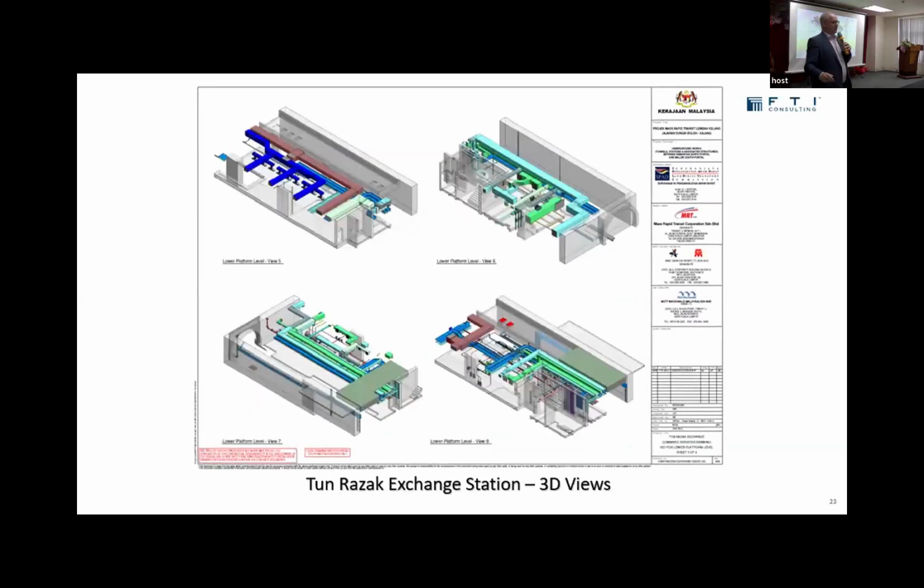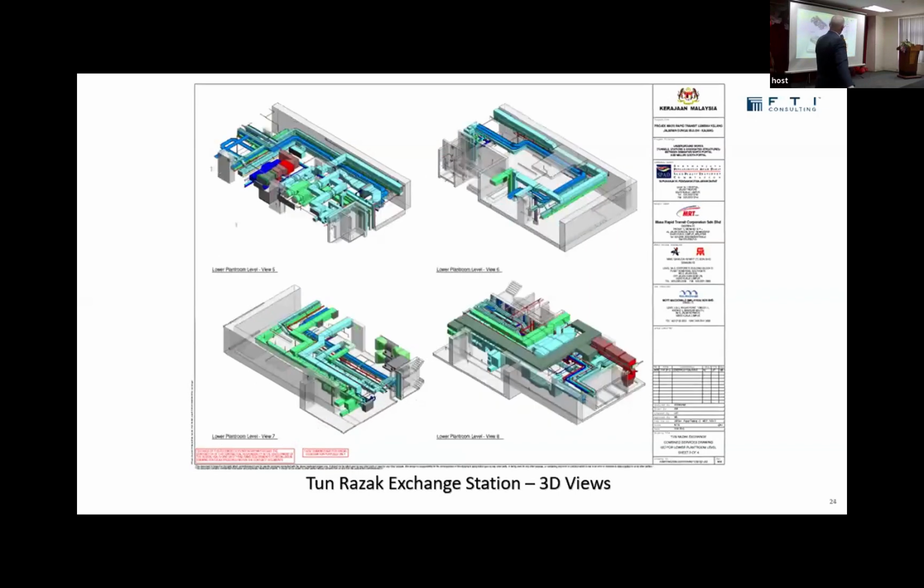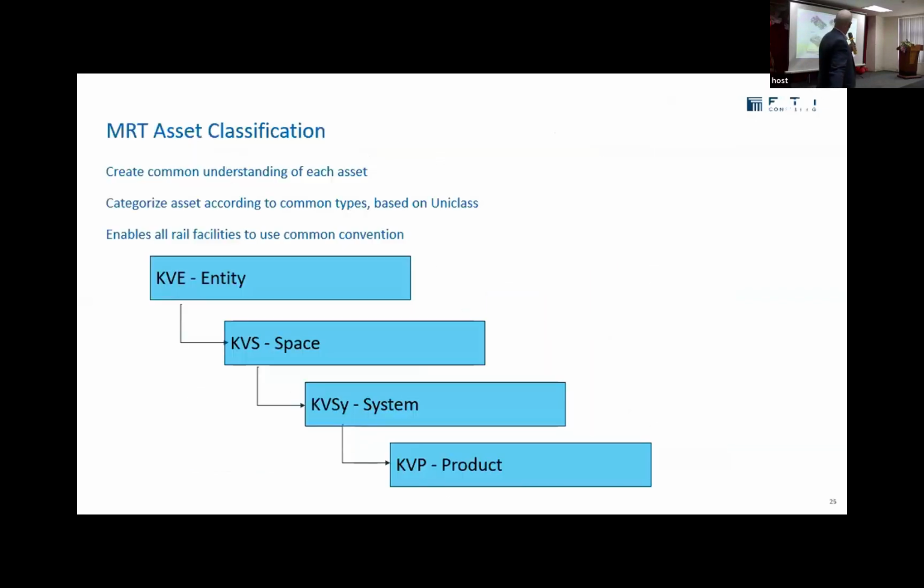But what's most important, and this is a challenge I'm going to set for you, on your next project, don't just settle for traditional 2D drawings. The plans, the elevations, the sections, that's easy in Revit. Also ask the design team to include isometric views. And you can do it per plant room, you can do it per level, you can do it in sections. But if you start producing these 3D views, you get more value from the process and more people will understand what's happening. So you can produce any number of 3D views.